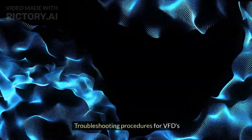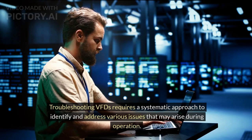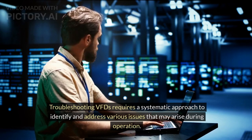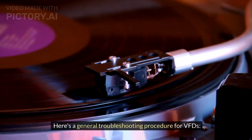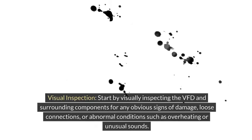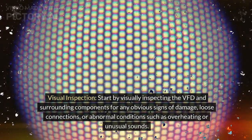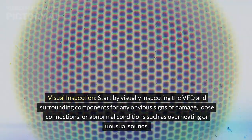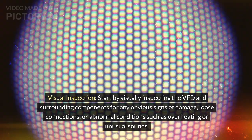Troubleshooting procedures for VFDs. Troubleshooting VFDs requires a systematic approach to identify and address various issues that may arise during operation. Here's a general troubleshooting procedure for VFDs. Visual inspection. Start by visually inspecting the VFD and surrounding components for any obvious signs of damage, loose connections, or abnormal conditions such as overheating or unusual sounds.